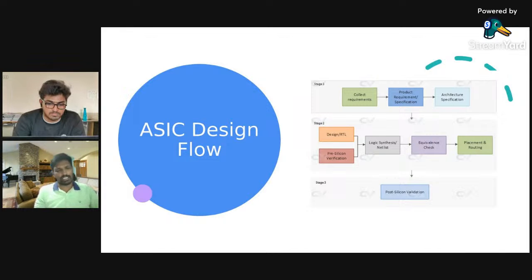This post-silicon validation typically requires all the features to be enabled, and to ensure that there are no bugs involved. So it's typically a complete flow, right from the spec, collecting the requirements from the customers, identifying the required features, and then putting it into an architecture spec, and then doing design and verification in parallel along with the backend logic synthesis, netlist creation, the GLS, the placement and routing, and the backend build. And then once you see that there are no bugs even in the post-silicon, you go ahead and release it to the market. So that is when you say a project is taped in, or it's PRQ'd. That's a typical ASIC design flow that is available. You can understand it in that way.